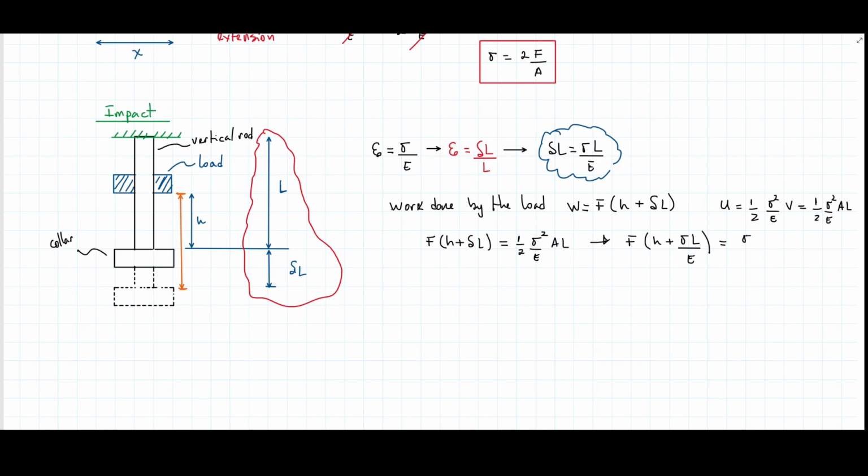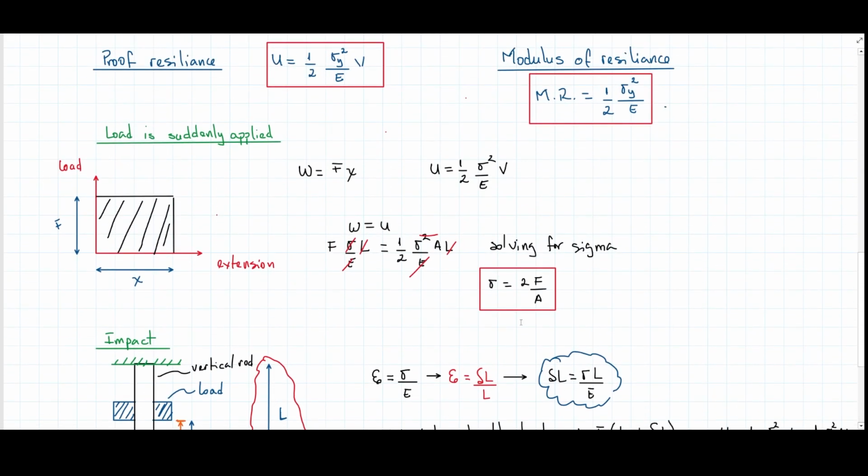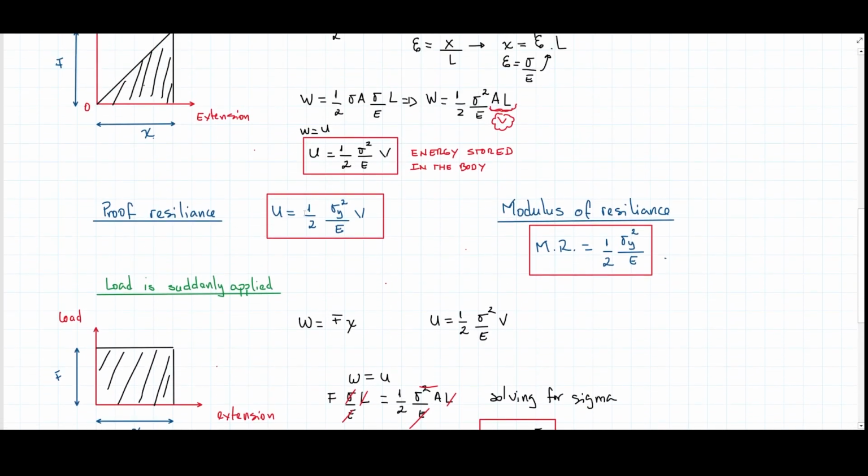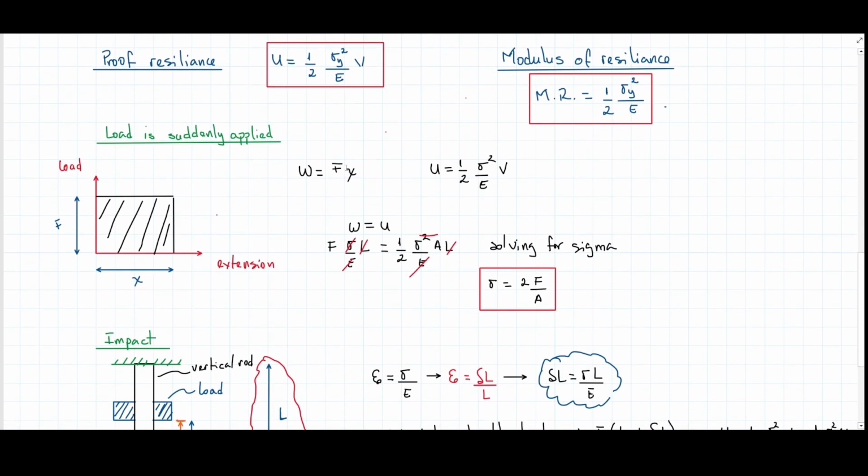And this equals to, let me write down like this, 2EAL length. Then I can start working with this portion that we have just written here to find out something similar to this, because in the end, the excuse we used to reuse the stored energy in the body was to find out certain stress relationships that we could use, again, to compare to certain things like the strength of the material, or to see if that's going to comply to certain levels there.